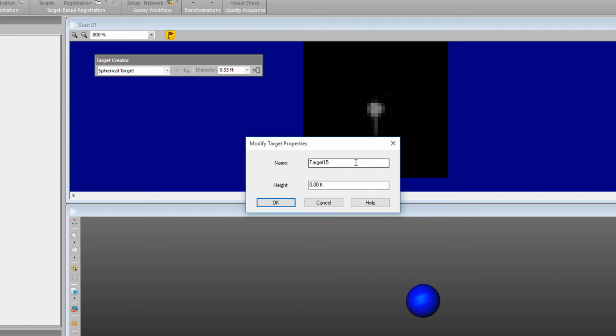They're all just targets, but again, for me, to keep it straight in my mind, I like to refer to it as my backsite, and I'm going to call this 000 because it's behind my station 1. Makes sense to me. And then I'm going to put in the height, so I used a height of 5 foot, and I find it easier just to highlight over the entire field and then just click number 5 and then hit enter. And I'll go ahead and put that in there.